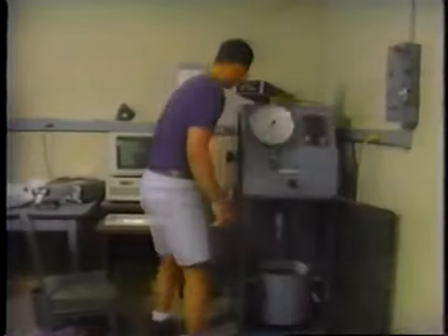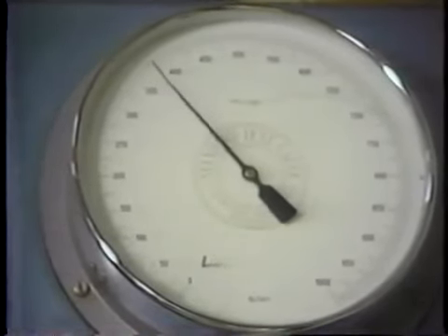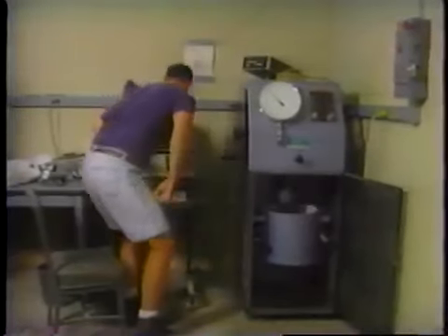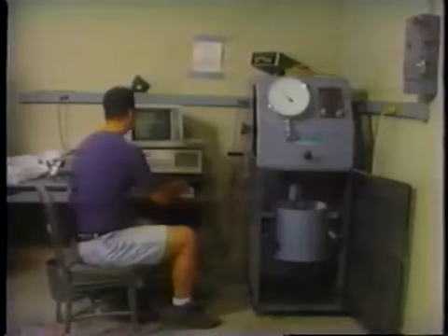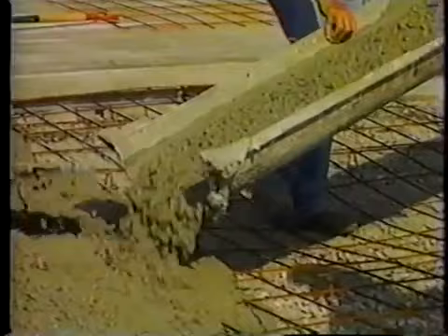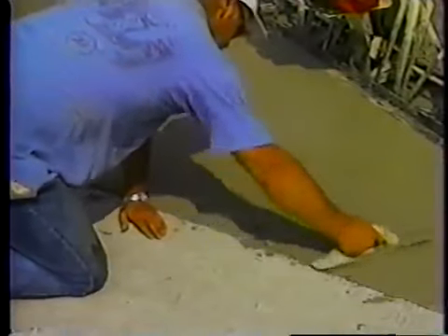Researchers use larger equipment, such as this Tattersall rheometer, to measure the properties of mortar and concrete. The rheological equipment can be used to measure the initial resistance to flow, which is referred to as yield stress. At the time of setting, the yield stress starts to increase abruptly, and the ability to flow is lost. Researchers are interested in flow characteristics to understand how the process of hydration stiffens the fresh concrete and leads to set in the concrete.